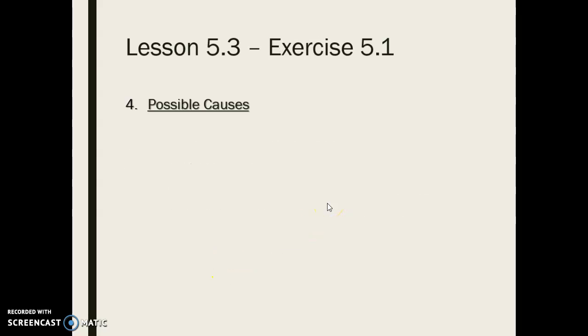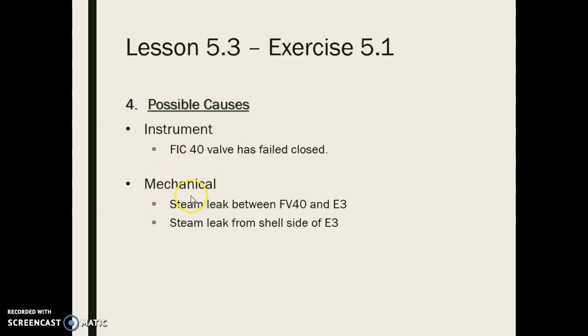I'm going to just give you a tip here. This is something that you probably wouldn't really have thought about, so let's just go ahead and try anyway. Possible causes. Instrumentation: FIC 40, the valve has failed closed, right? That's our steam. We think that might be one of the cases here. Mechanical: there could be a steam leak between FV40 and E3. So that's between this valve and E3 if this valve isn't closed.